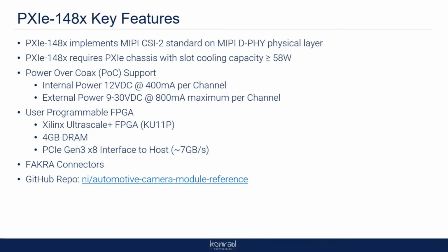So that's all good. There are instances, though, where we've had customers need higher current, lower power. And in that case, you cannot use the power over coax on the card. You need to completely keep your camera power separate from the card. So the key is to watch the current draw, because this 800 milliamps isn't a lot, and neither is this 400. A lot of the cameras I've seen run at 12 volts DC, but they may pull half an amp. So just be cautious of that. It won't fry the card initially, but you want to make sure you're not going to overdo it.